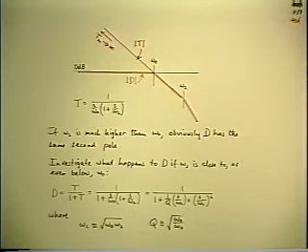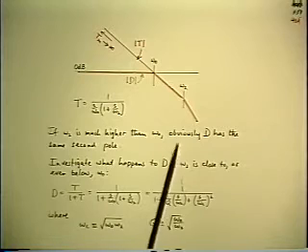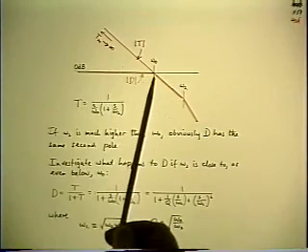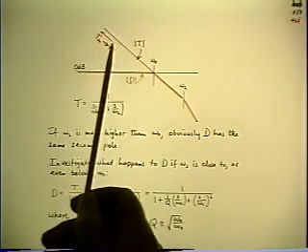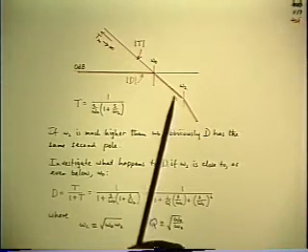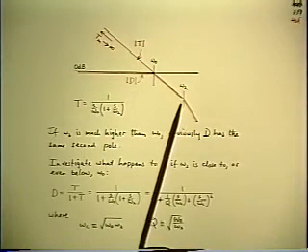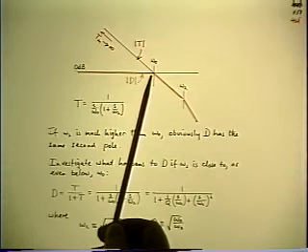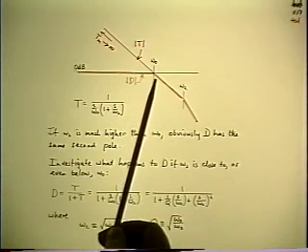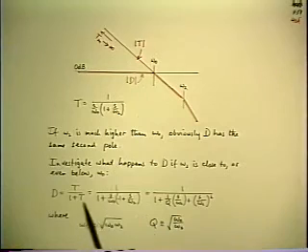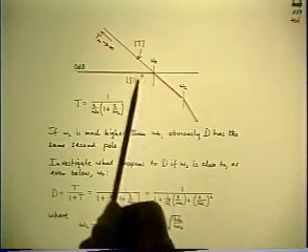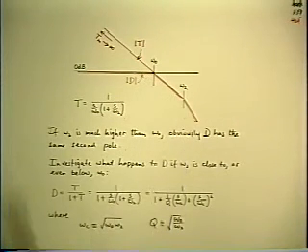Qualitatively, it's less than 90 degrees. You evaluate the phase lag at crossover, which is minus 90 degrees from the first slope of T, and then there's a little bit of extra contribution from the second pole that's further up. So the phase lag is a bit more than 90 degrees at crossover, therefore the phase margin is a bit less than 90 degrees. So you associate a phase margin less than 90 degrees with a little less desirable shape of the closed loop gain.